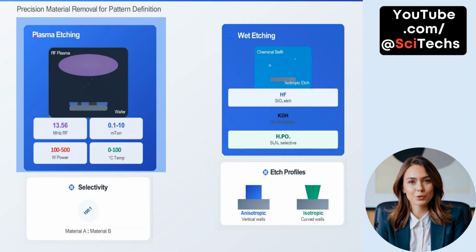Precision material removal for pattern definition. Etching is a key step in semiconductor fabrication used to remove specific materials with high precision. Plasma etching, also known as dry etching, uses RF plasma to generate reactive species that etch the wafer. It operates with a 13.56 MHz RF frequency, in a pressure range of 0.1 to 10 millitorr.